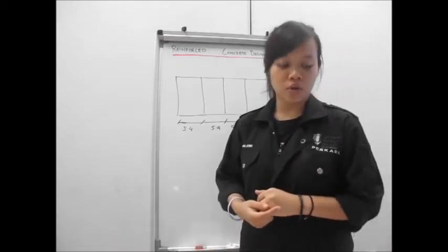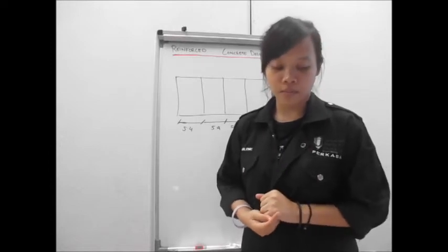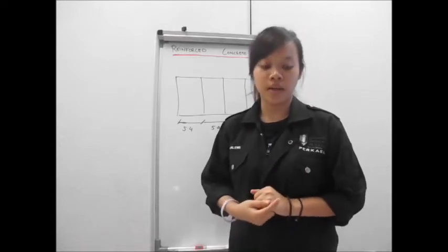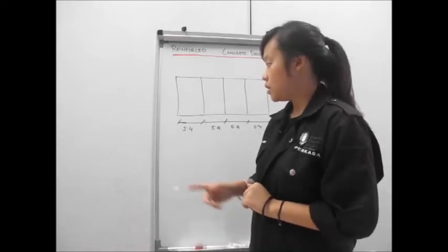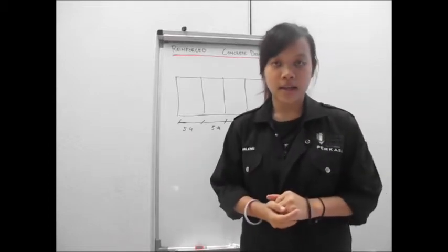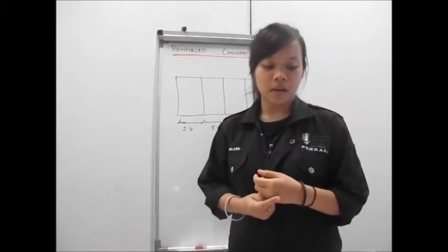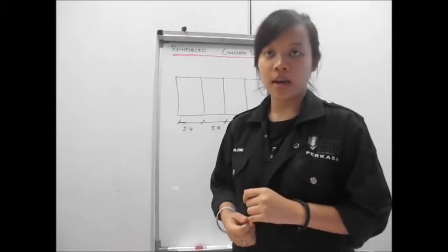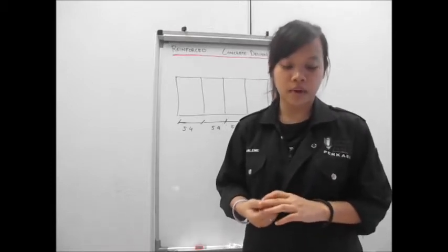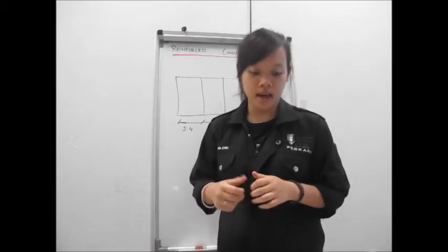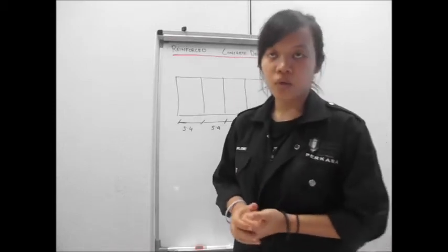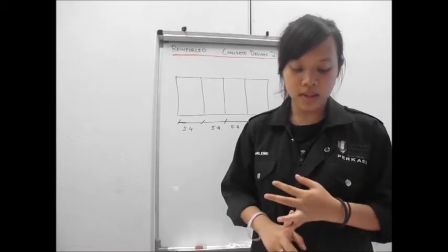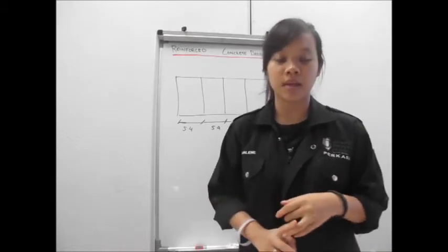Then we need to find the durability, fire and bar requirements to find the C nominal that we use for our analysis. Then we find the action for our slab using Qk, Gk, and 1.35 Gk and 1.5 Qk. To do the analysis, we consider the shear force and bending moment itself.